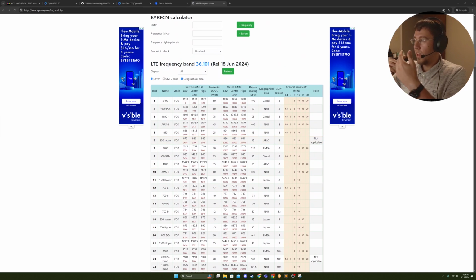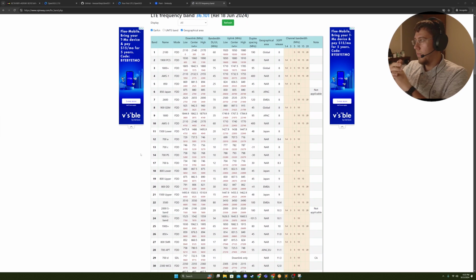So basically you've got two links. One frequency band is essentially used for the downlink, which is from a base station to a UE, and then a different frequency band is used for the uplink, which is the UL. The RAN itself will derive the uplink frequency from the DL. So if I use, for example, 5230, which is 751 megahertz, then the UL will automatically be derived as 782. So as long as your internal clock source is well equipped, then it will be able to maintain these frequencies just fine.